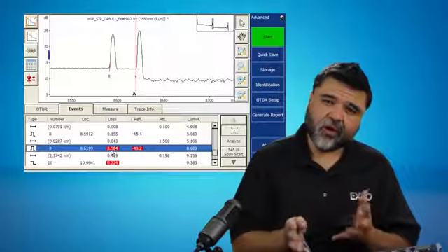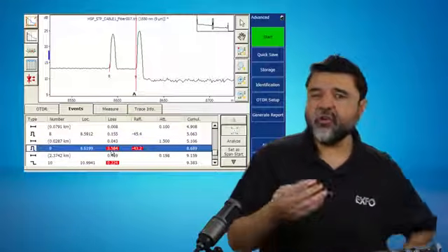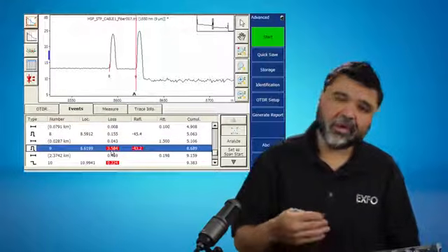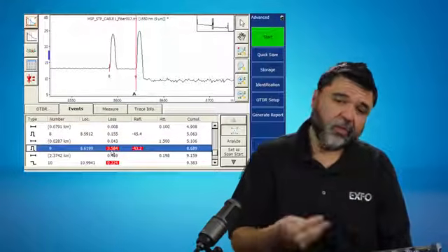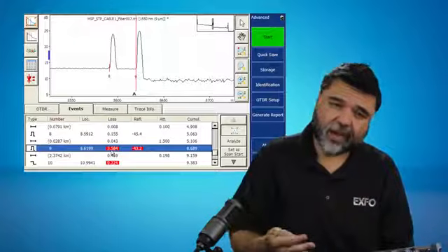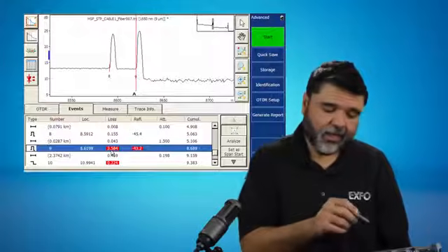And so this is where an OTDR really starts to see its value, is to help you reduce your mean time to restore or mean time to repair by allowing you to troubleshoot appropriately. Because typically what you'd end up doing is just cleaning fibers or swapping cards until the system starts working again. In this case here, I know there's something wrong.